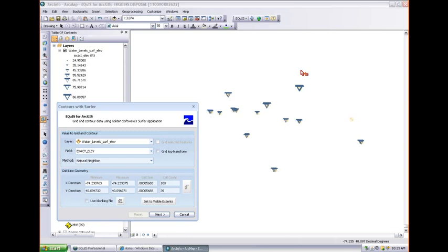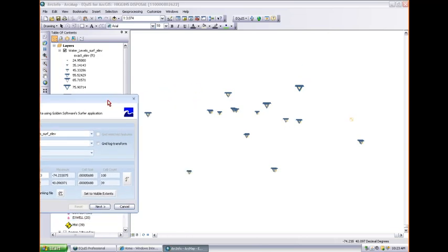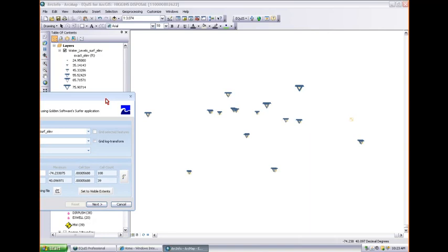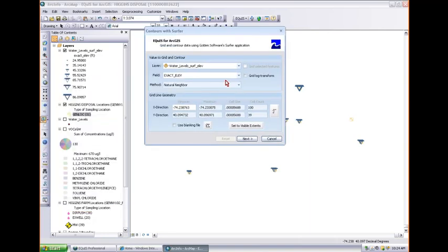Yeah, it's all in the Surfer help, and I think even online on their website they go into the benefits of each one, pros and cons, with example drawings. But the cliff notes is kriging and natural neighbor. Kriging if you're doing a square area that you're not worried about over-extrapolating where you don't have data. But if you've got an irregular shape or scattered points far away with nothing in between, natural neighbor you'll get the best results with, just from my experience.